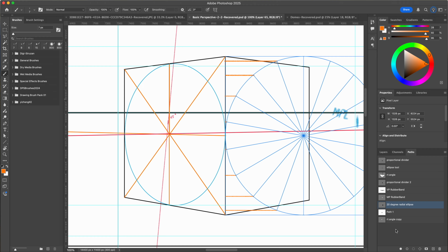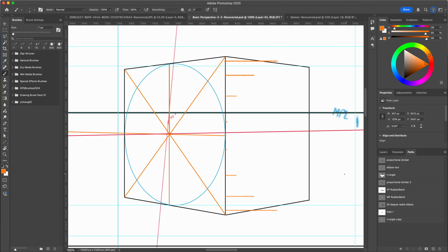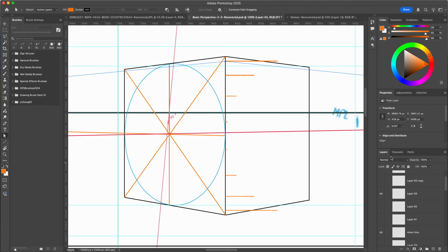All right. So I'm going to turn that thing off, and what I'm going to do instead now is turn my vanishing point rubber band tool on. Now remember, with this thing, I have this center point here. I'm just going to leave it centered along this spine here, and each of these edges, this line is going off and it's locked down to my vanishing point right, and this line is going off and it's locked down to my vanishing point left. And so I know that I've got perfect degrees on this. So I can come up here to this line here, and I don't have to draw all these lines. All right.